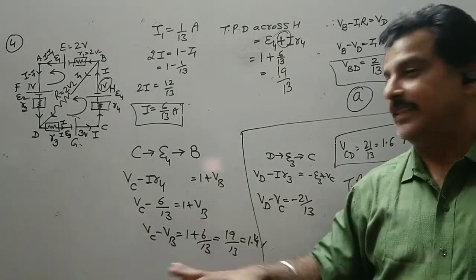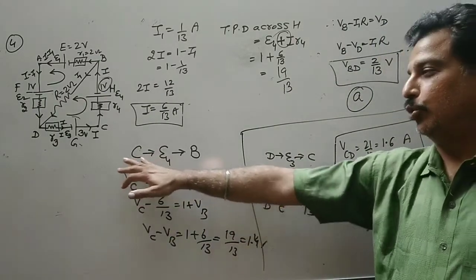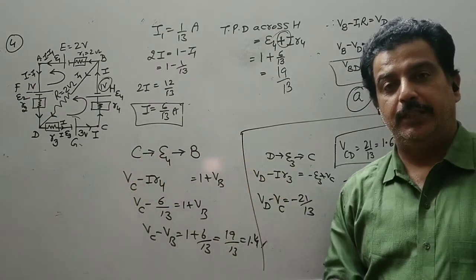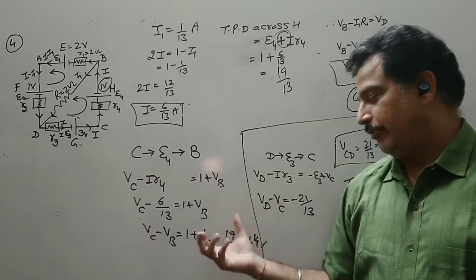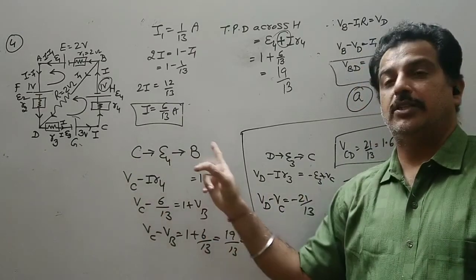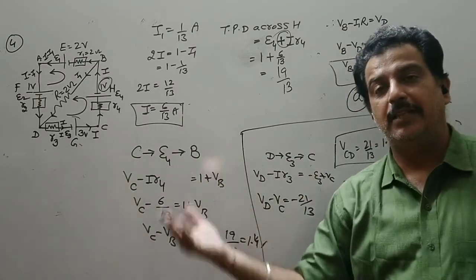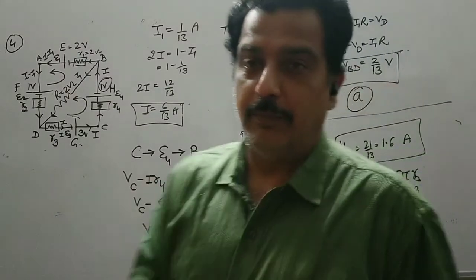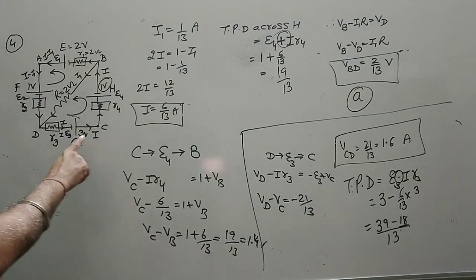Otherwise, the safe side is to apply Kirchhoff's second law to the open path. You start from one point and stop at another point, whichever. If you get a positive answer, then C potential is greater than B potential, else the opposite. Otherwise, remember charging and discharging: in discharging, current is given; in charging, the current is drawn.